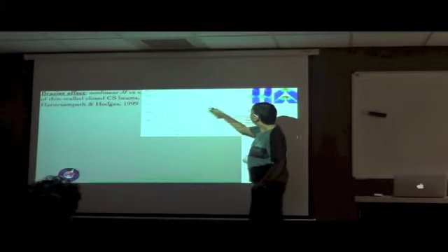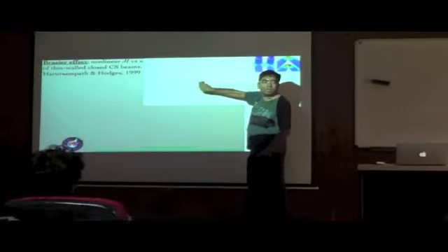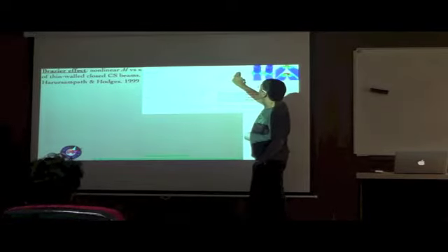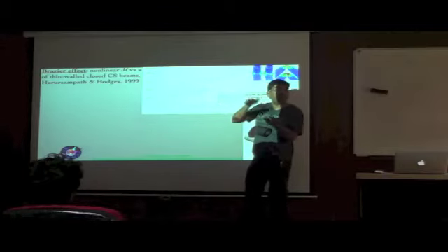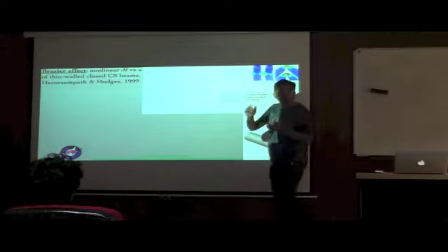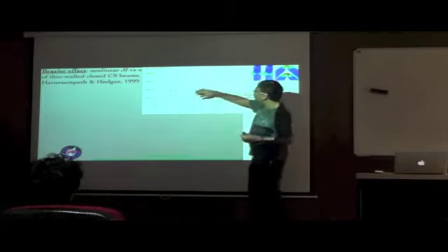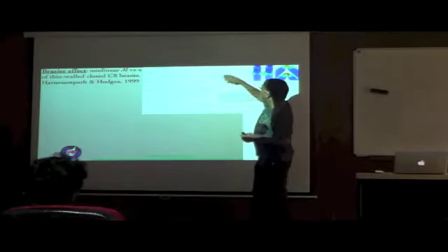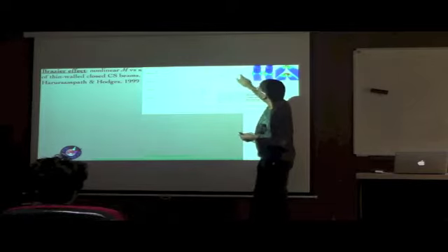Just the difference between these two, for example, is that here you have the outer plies as plus or minus 45. Here you have the outer plies as 0 degrees, and you know that in bending, the outer plies play a much more critical role because they contribute more to the bending stiffness, being farther away from the neutral axis, and therefore you see a much larger moment that it is capable of taking. So that's basically what you see over there.